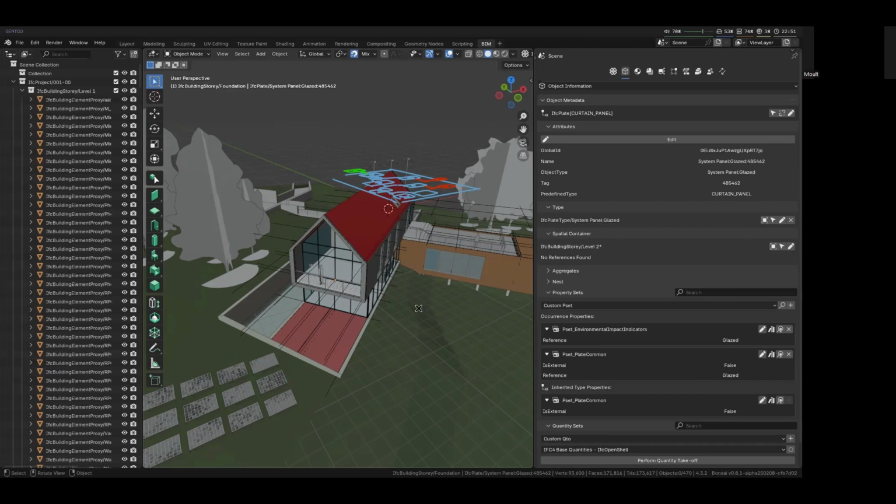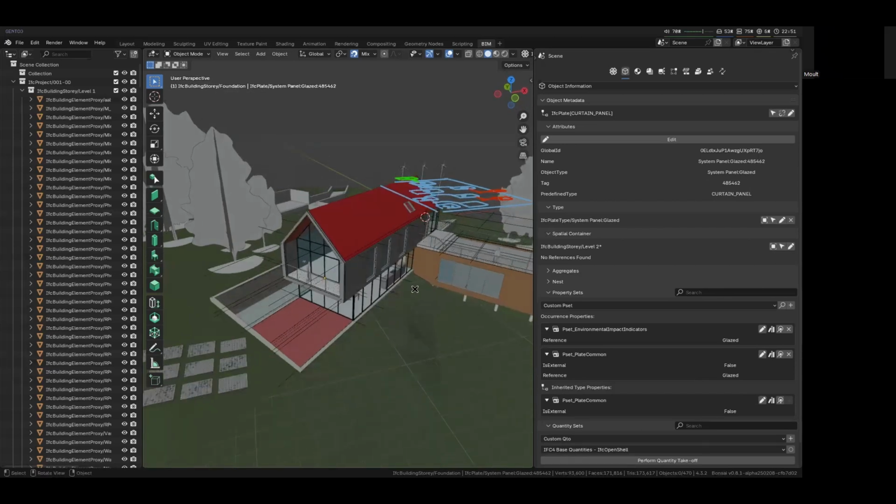And the idea back then, and this happened in IFC 2x3, so it was a very, very old idea, was that if you had a wall or a slab or a door or a window, in 90% of cases a wall is always going to be the kind of stretched out box that's extruded up, and it has layers in it that inform its thickness. And that's the simplest wall. Same with the slab. You've just got a box.